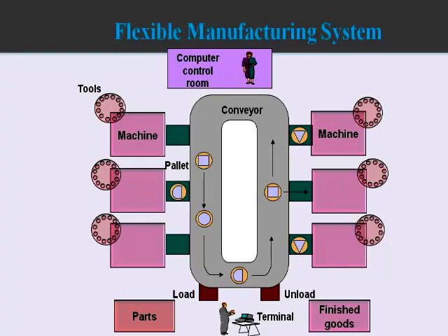Pallets are automatically placed with automatic setup dock pins. The pallets will be located on the machine. So as and when a particular part is loaded on a machine, the part will be read, and accordingly the particular program for that part is loaded, and the machine starts processing that program. This goes on.